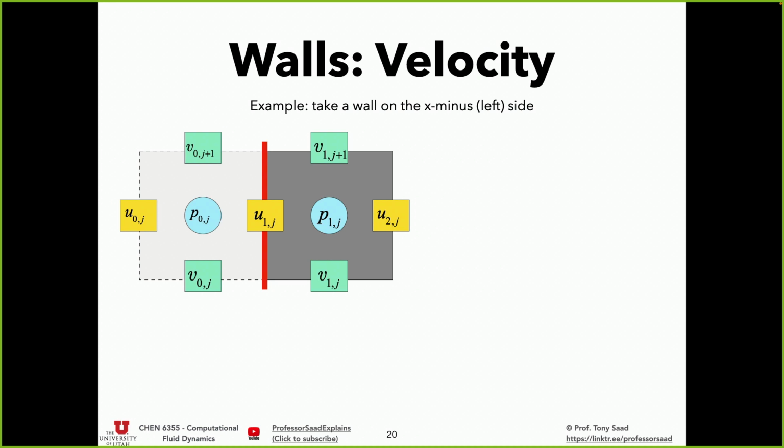Okay? Now, in general, at a wall, the normal component of velocity, in this case for an x minus, so let's do it for a specific case, and then we will generalize. The x minus face, u is 0, because it's a wall. There's no flow coming in. Okay? If it's an inlet, u would not be 0. It would be a different condition. Okay? So u is 0.